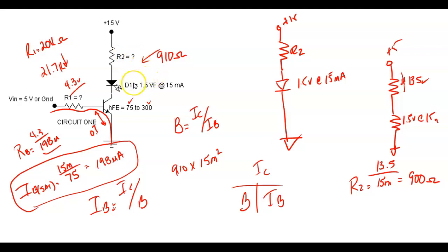So here, since this guy drops, and we assume the transistor's dropping 0 when we saturate, right? We assume when it cuts off, it's dropping the entire voltage. When we turn it on or saturate it, it's dropping 0, even though it's not. When we look at the data sheets, we'll see it's got a saturation voltage, but it's always going to be less than 1 volt.